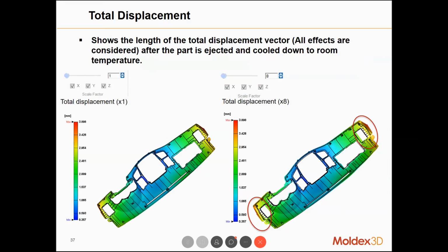So basically, you can look at the warpage displacement results by isolated x, y, or z direction here. And we can also utilize the warpage deformation tool to raise the scale in order to get a better visual sense of what the warpage trend is. So sometimes the one-to-one scale is hard to see that the part is warping.